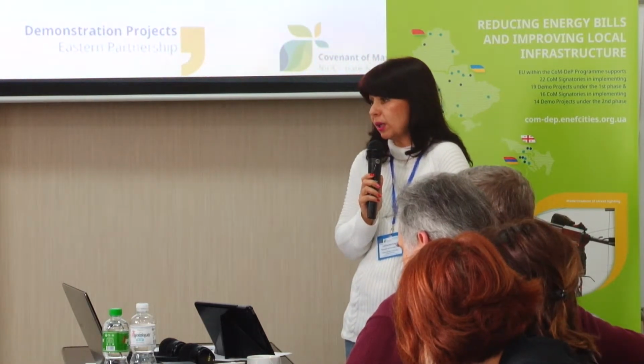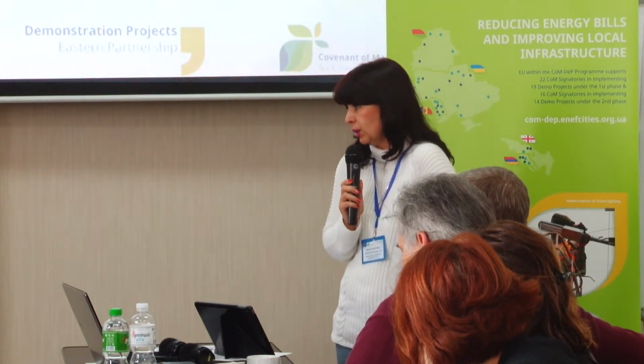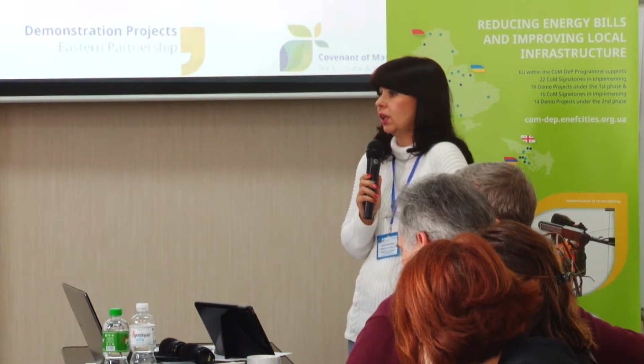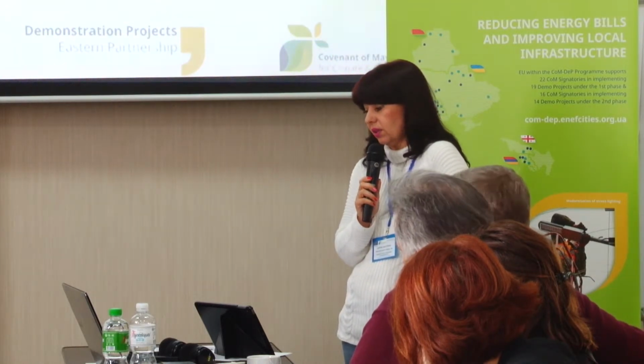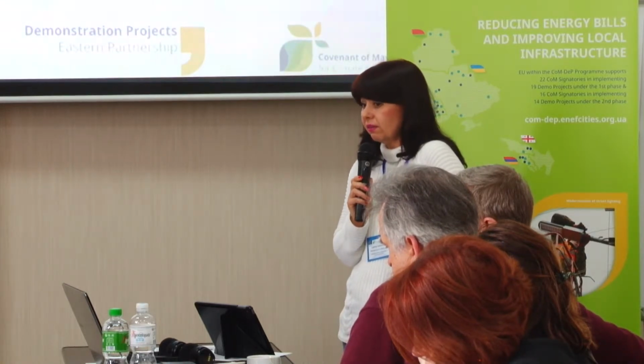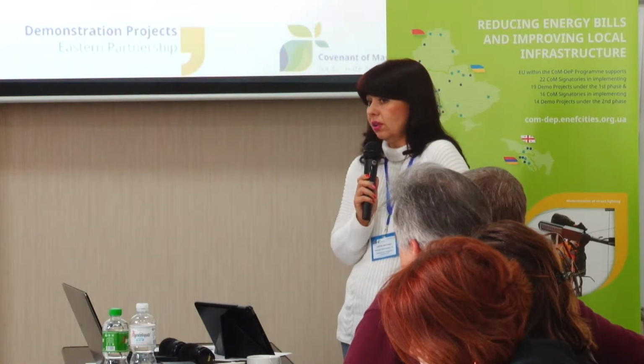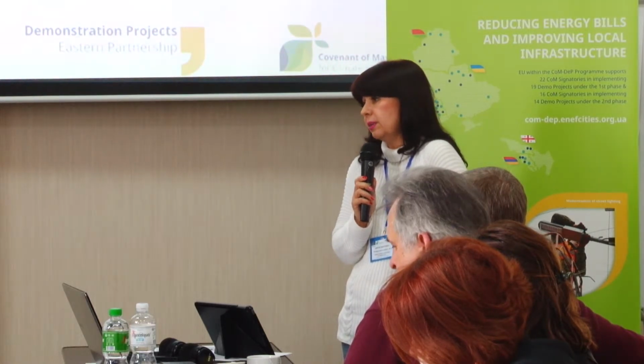And therefore, our project has special admixtures. So gypsum plasterboard can be done within a month, but this finishing which we apply and those admixtures which we apply need about 3 months. So you have also to coordinate this. And there can be a lot of things like this.